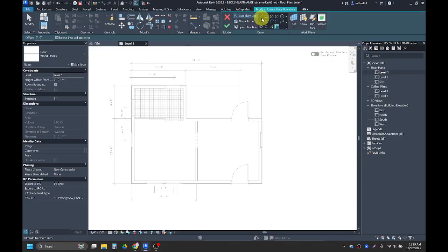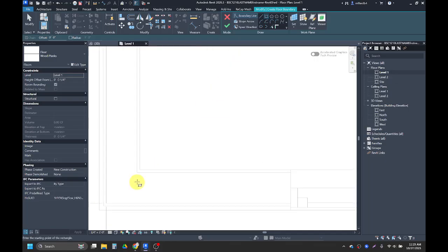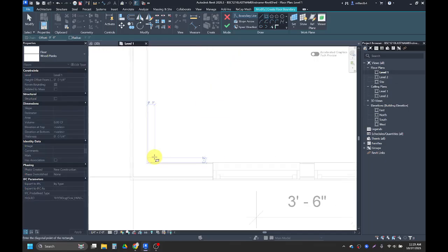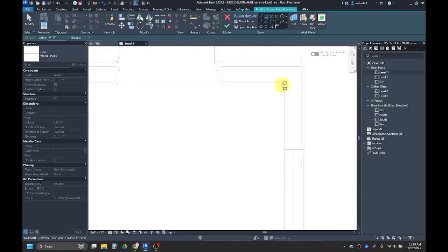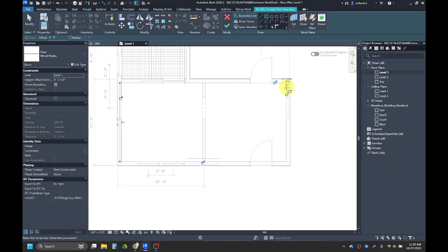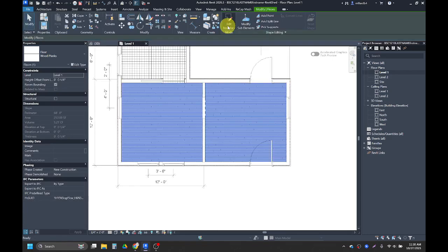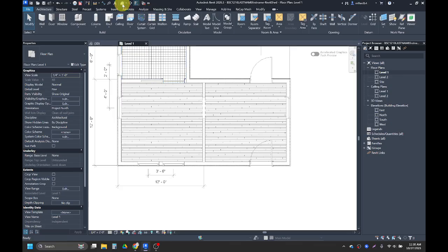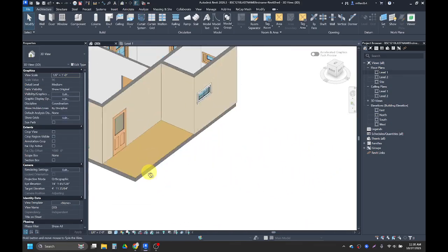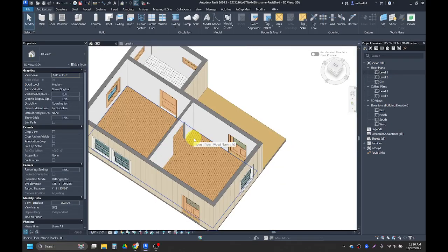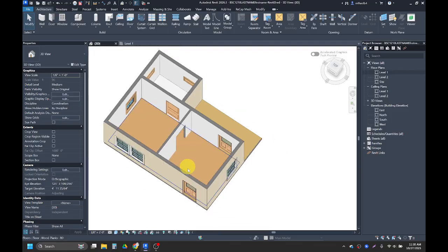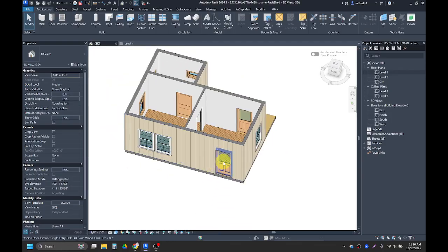And this time, instead of using the line tool, I'm just going to use the rectangle tool to draw a rectangle from one interior corner of my building to the other interior corner of my building. And then again, I'll hit my green check. And now I have wood flooring or wood planks inside my building on my finish in there as well. So that's just how I like to do finishes. There's a bunch of different ways they can be done though. Now, let's hit escape a couple times just to make sure we're not in the floor tool.